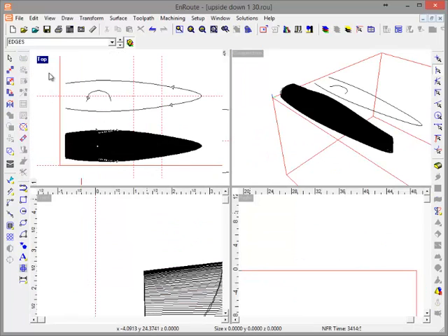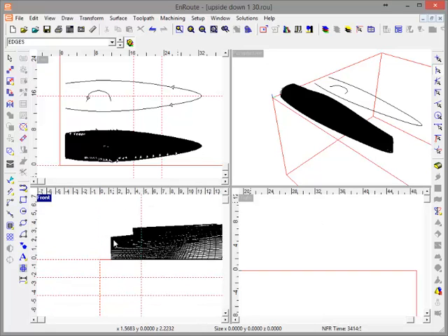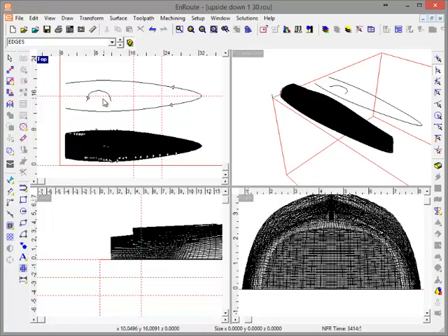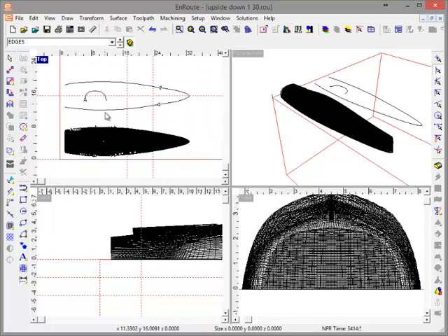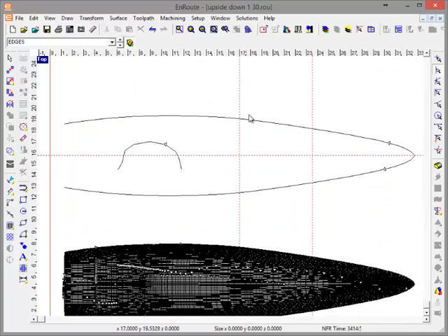I went to the side view of this part and kind of went here and selected this, and I went to the side view here, and I basically just went through here and got a profile, and then I did a sweep to rails. Now this is not going to be the same thing as what they provide you, but it'll give me something to work with for this example.